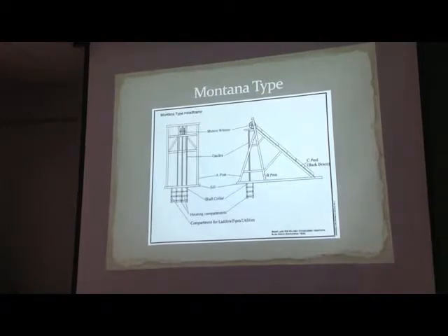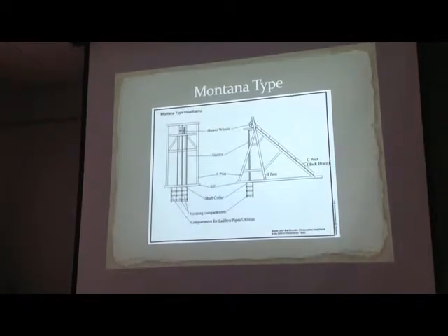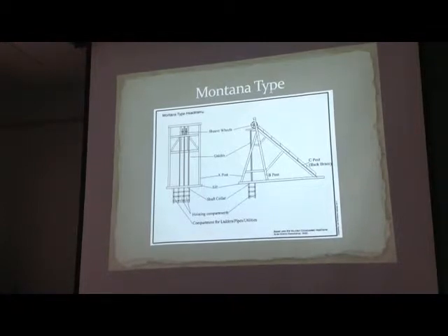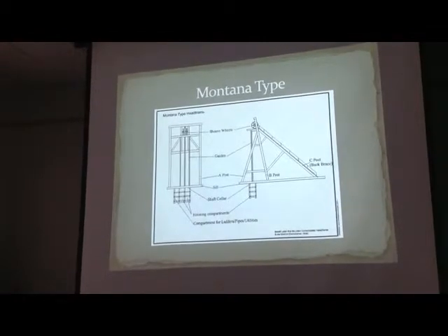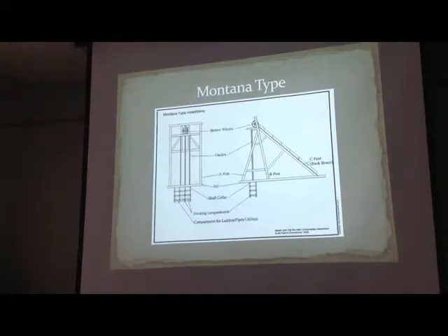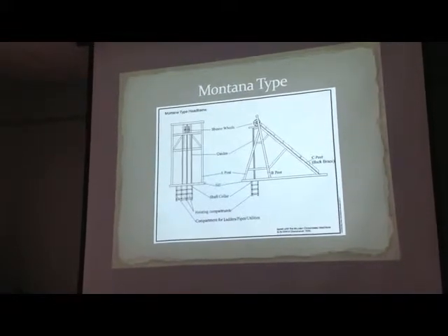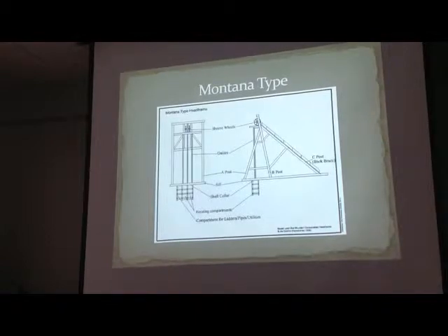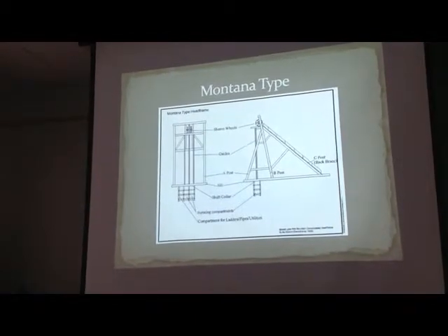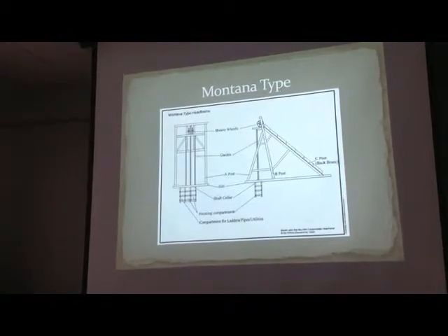Once again, from the front it looks like a 2-poster, but when you get to the side you'll notice that the main legs are inclined forward towards the shaft. The legs in front of the shaft are inclined backwards. The A-post is towards the hoist, the B-post is away from the hoist. And the back brace is standard. This particular drawing is based on the Mountain Con head frame, the wooden head frame. And in this case, the resultant would have fallen right in between the 2 legs. The distance was longer here because of where the hoist was placed.